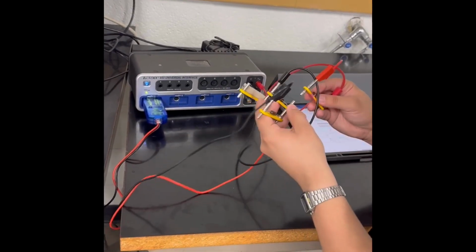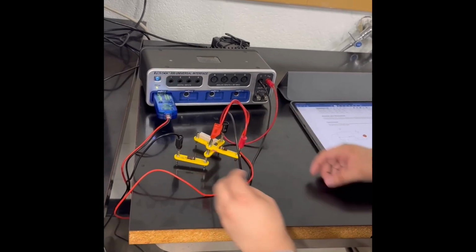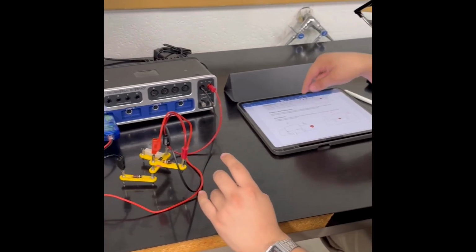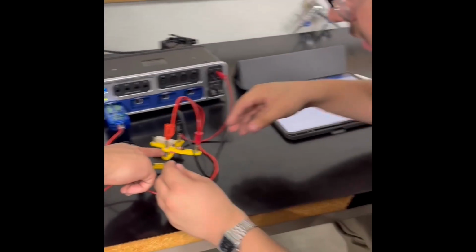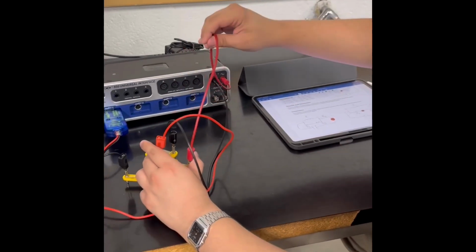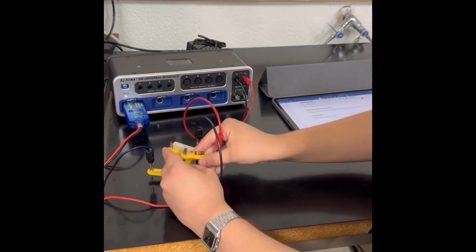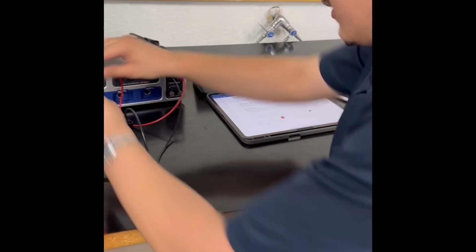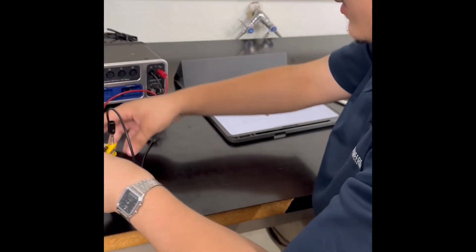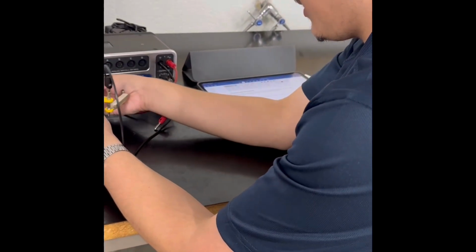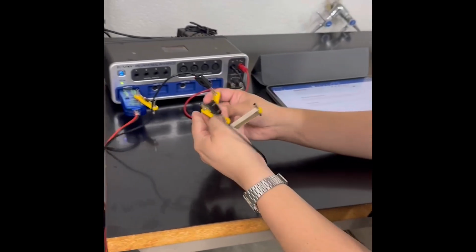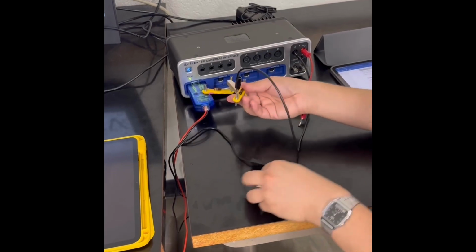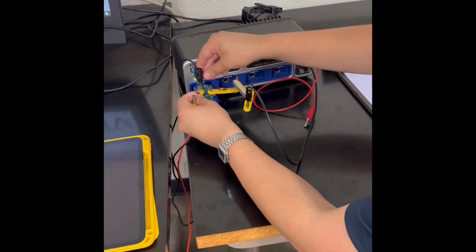For resistor 1, we were trying to find our voltage and our current for every single resistor up to resistor 4. Resistor 1, we got 0.39 volts, with the current being 16.5 milliamps. Resistor 2, we got 0.14 volts, and our current for that would be 6.9 milliamps. Resistor 3, it jumped up quite a bit, it went up to 1.78 volts, and our current stayed the same at 6.9 milliamps.